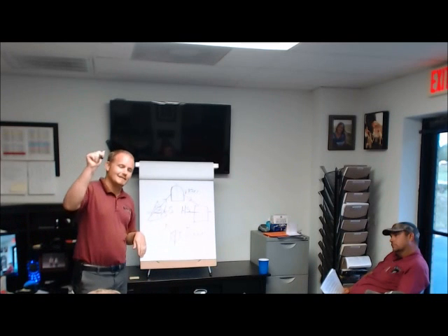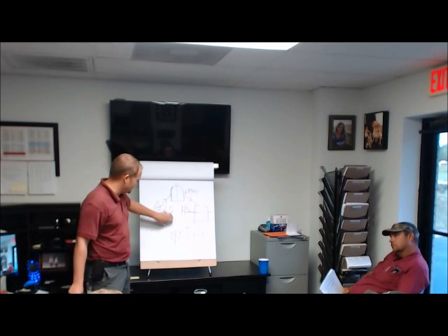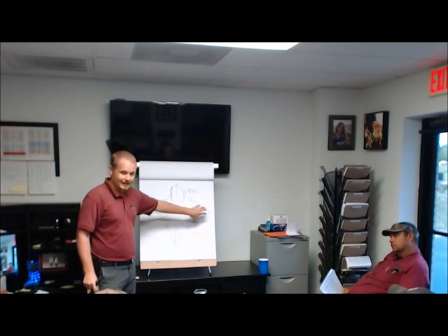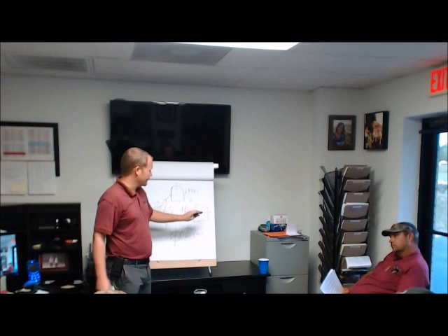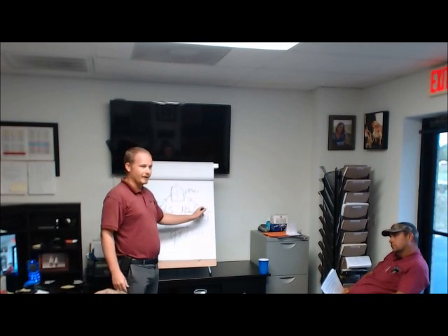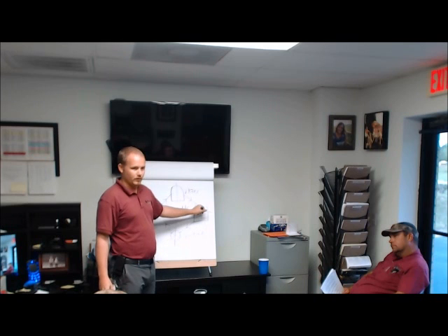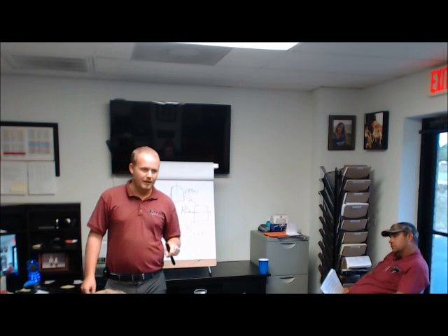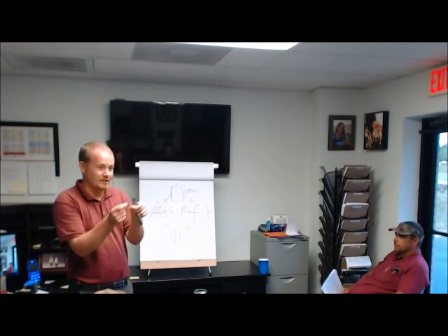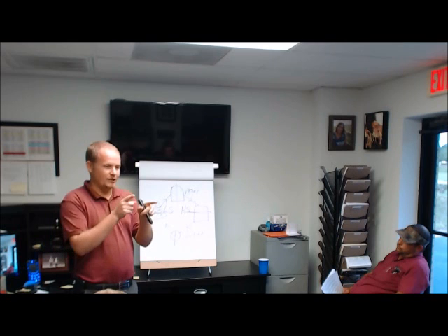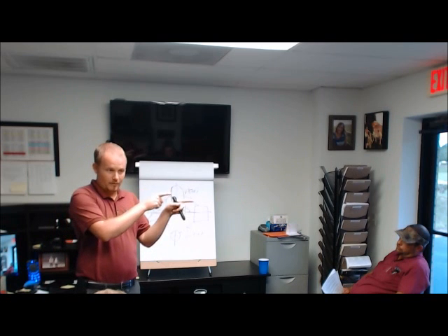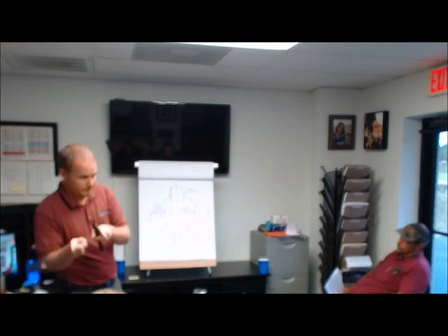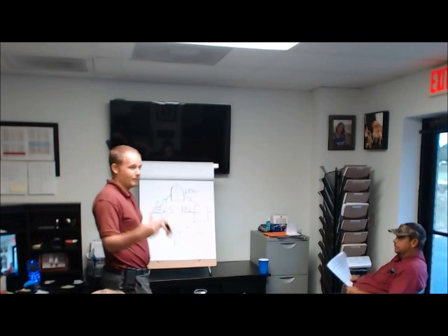It's not necessarily flash gas. It's flash gas when we're talking on this side of the system, but in the condenser coil, it's also saturation. If you were to take your thermometer and get a good reading right in the middle of your condenser coil, you would be reading the same saturation as you can read on your gauge, as long as you can get them close to each other. Because at that point, you're reading it changing state, but it's the other direction. It's changing state from a vapor to a liquid. So at that point, it is condensing.